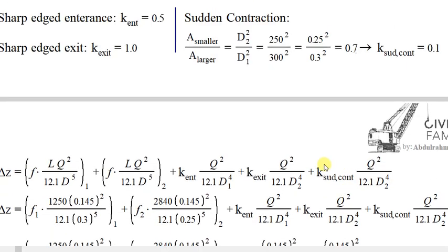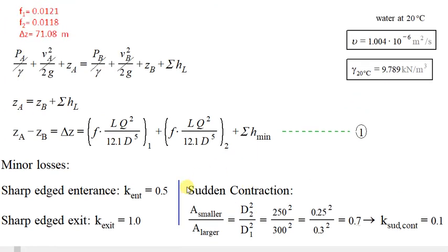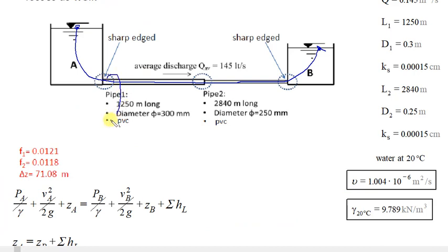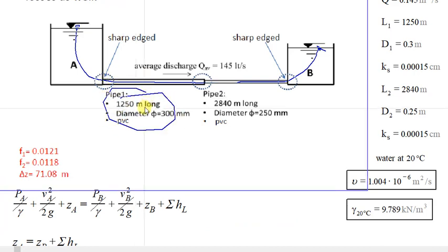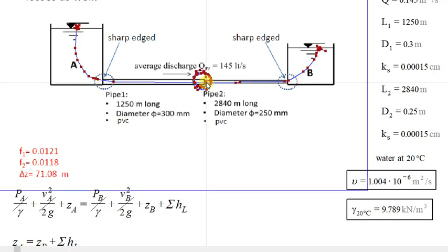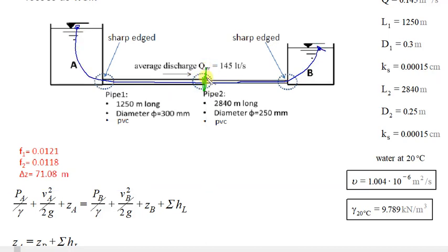Anyway, coming down, then how much should I multiply each of these K? The 0.5 entrance with the area of this one, which is the pipe 1. Velocity 1, because velocity 1 is just at the location, and at the exit it's same. Also properties of this one, which is the diameter 2 should be used, and velocity 2, I mean. But when it comes to places, we have two options. For example, here we are at sudden contraction, but we don't know which properties I should take, velocity 1 or velocity 2, which means also diameter 1 or diameter 2.